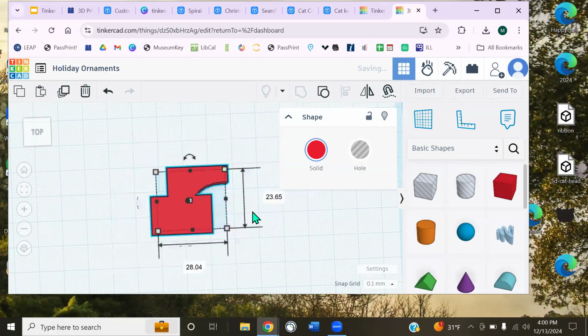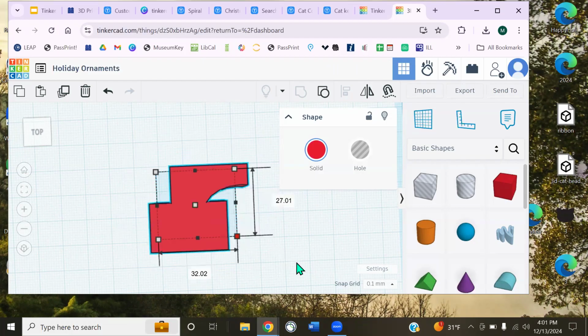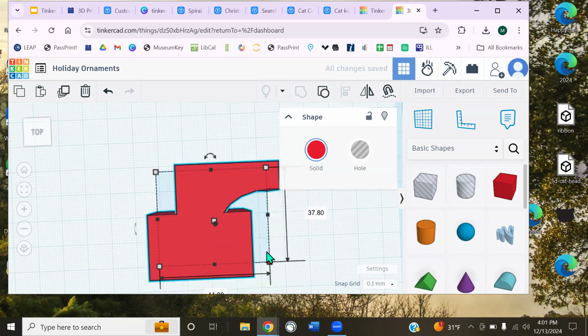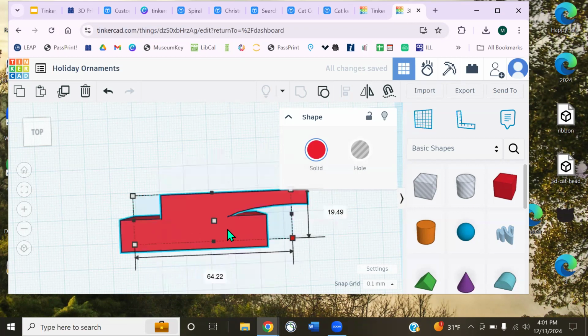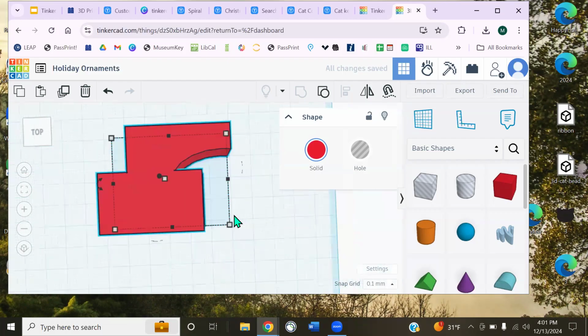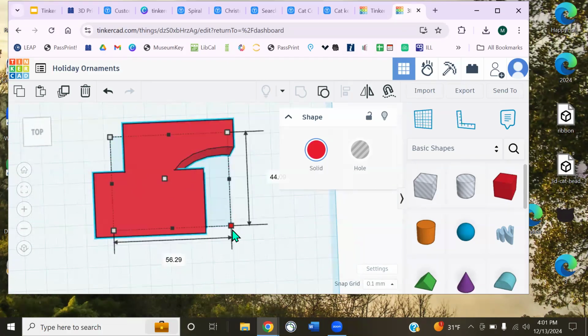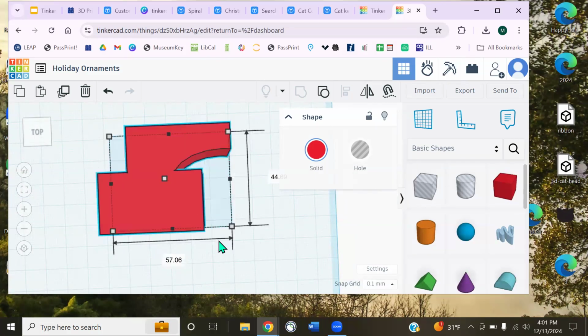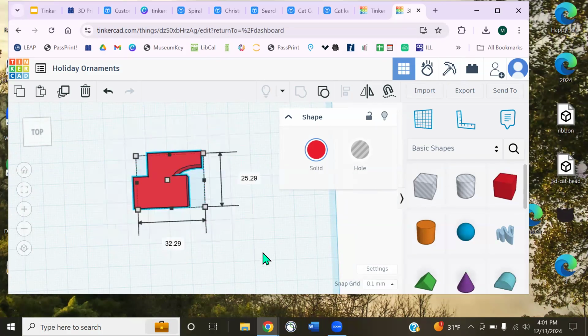So it's keeping it in the same place on the design, but scaling it up and down from the middle of that object. This is my Shift key. This is my Alt key just by itself, a little bit wonky. But usually anytime I'm designing, I'm almost always holding down Shift and Alt at the same time. I can skew it up and down and keep the same shape and do it from the middle.